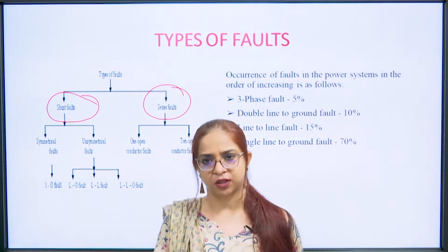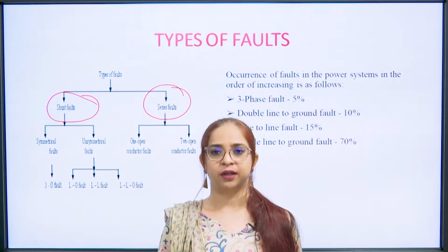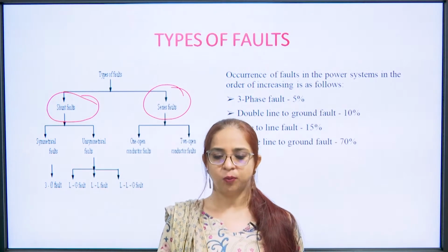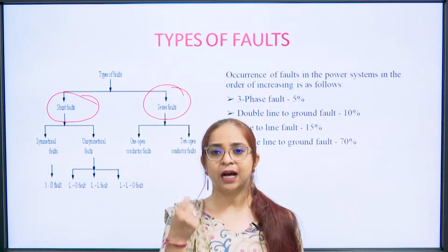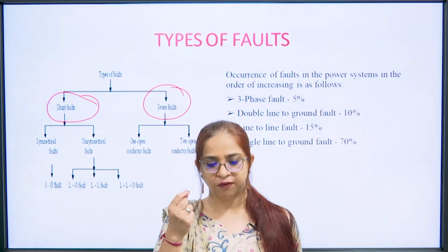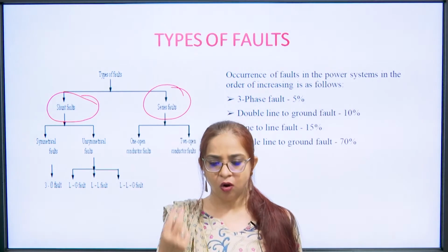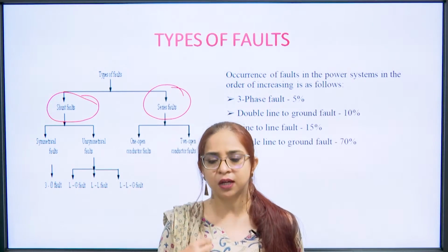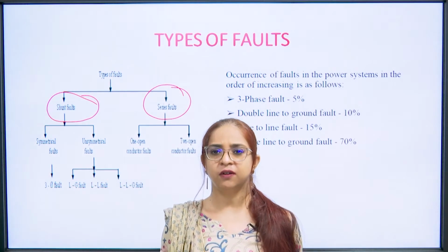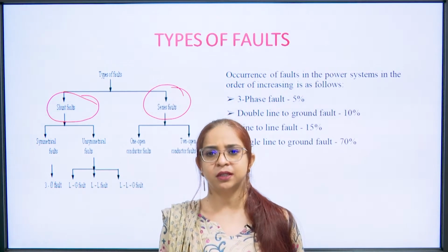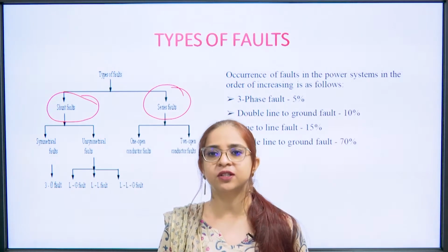Serial fault में क्या हो सकता है? तो possibility serial fault में क्या है? ओपन सर्किट होने की. अब serial faults में ओपन सर्किट होने की possibility है, तो what are the chances? The chances are either a single phase या one conductor is in faulty position and it gets open circuited, or maybe in three phase two systems are open circuited. You will ask why not three? If there is three phase, all the things are open, that means it is not under operating condition. We are talking about operating condition में क्या हो रहा है.